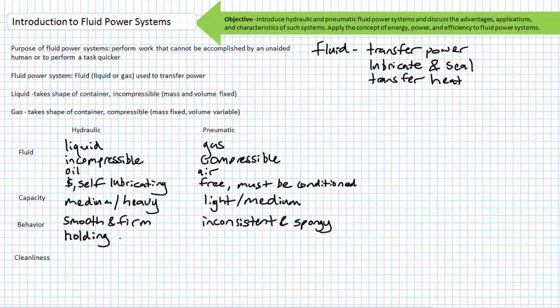Pneumatic systems must account for the compressible nature of gas. Mechanical systems must account for backlash between gears or play between mechanical linkages. Electrical systems don't really work well in static situations and often can only decelerate objects in the process of actually moving. Hydraulic systems, in contrast, are perfectly suited for such static applications.